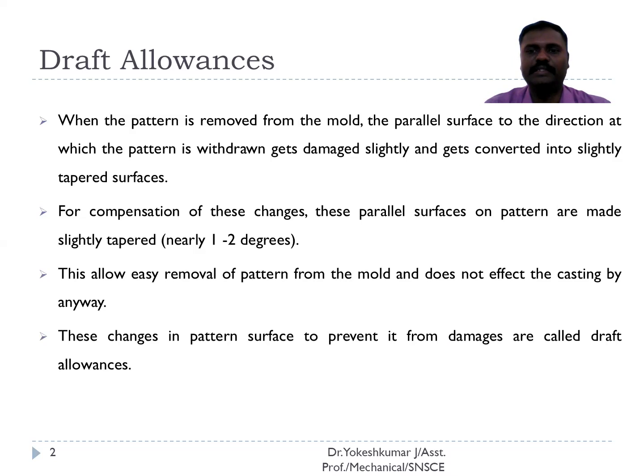To compensate for these changes, especially with very deep vertical surfaces, when the pattern is removed, some dimensional changes occur because we need to slightly adjust the pattern to remove it from the mold. So these parallel surfaces can be slightly tapered by 1 or 2 degrees for easier removal or withdrawal of the pattern from the mold.